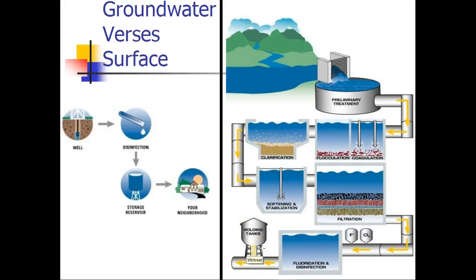And when we disinfect, chlorine is normally the disinfectant of choice. We always want to make sure that we get past the point that we've done all the kill, but there's some extra, and that extra is called a residual.